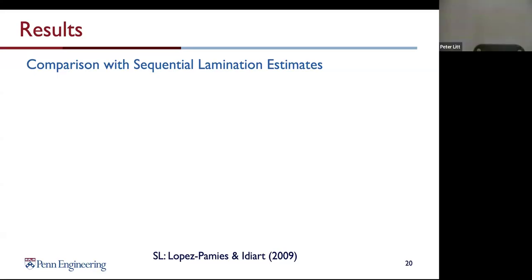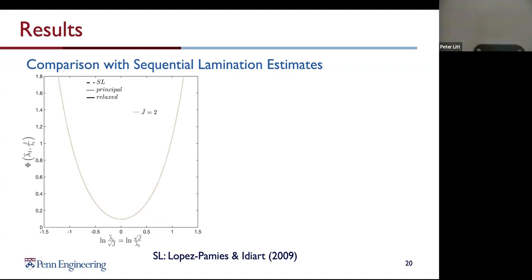You get a nice tidy formula when you do that, but when they published this, they noted that the result you get for the energy is polyconvex. So it doesn't have the possibility of these types of instabilities that we saw here. And so we'll see what that looks like when we compare it with ours. We're going to plot these cross sections of the energy for a constant value of the macroscopic J bar, so your volumetric deformation, and then in terms of this, which is basically a measure of how much shear is in the material.